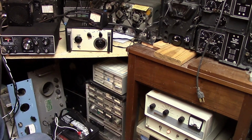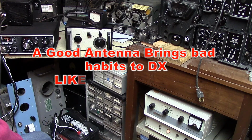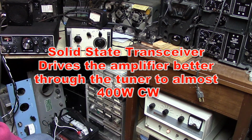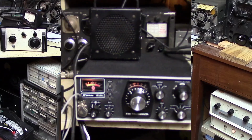811s of any brand, I guess. I didn't really look in there to see what somebody had stuck in there, but I can tell you they are the original 811 tubes that came with the amplifier. And I've done quite a bit to the amp to settle it down. I put a step start in it, which basically allows the tubes to light up a little bit and the high voltage to come up slower. And I also improved the bias circuit on the linear pretty drastically. It was quite primitive. They took the 6.3 volts for the tubes and grounded one side and developed the bias with a diode.